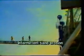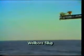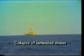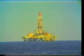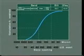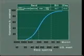For example, problems experienced in the Gulf Coast have been due to fine sands plugging the screen, high flow rates with intermittent sand influx eroding the screen or liner, movement of sand and shales into the wellbore causing a reduction in permeability, and the collapse of shale layers laminated in the productive sands, resulting in the production of solid materials called fines. A plot of formation grain size on semi-log paper indicates the percentage of sand retained at each screen size in the sieve analysis versus various sieve openings on the log scale.